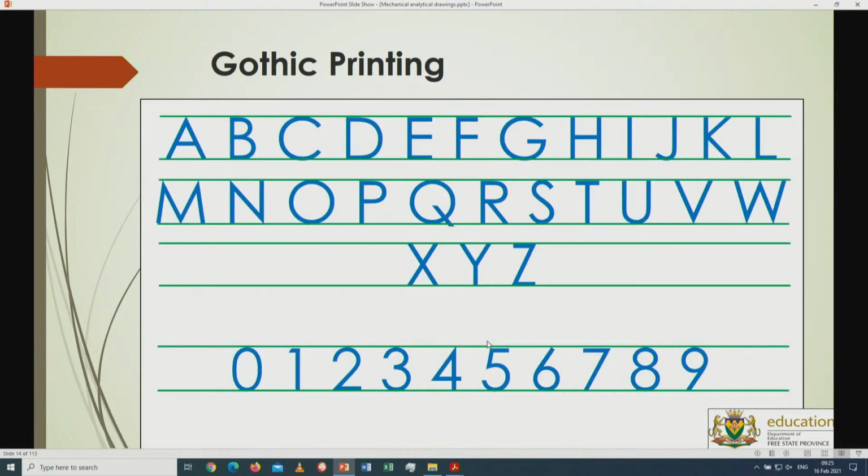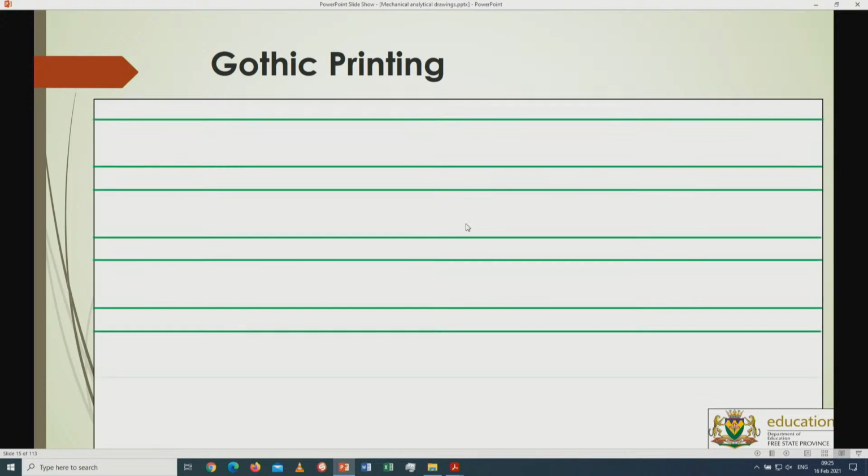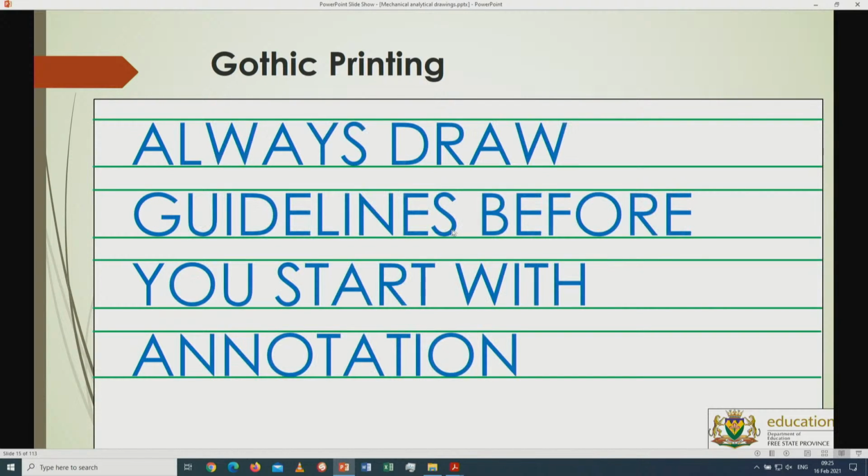And then if you do the lettering, just remember that the lettering is normally like Gothic printing. If you go to your computer, the lettering that you will see over there. There we go with that. Arial is also very close to the correct style. There's a few things that you have to understand about lettering. You will always draw neatly right in between guidelines. Normally the guidelines are forming the fence lines that it doesn't go over. Like for instance in the case of a Y, you're not going to go down the line, it's all between the guidelines over here.